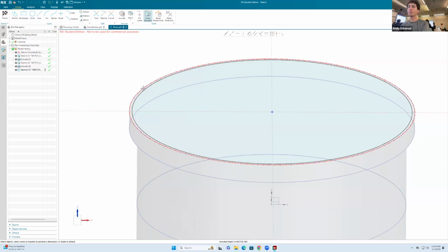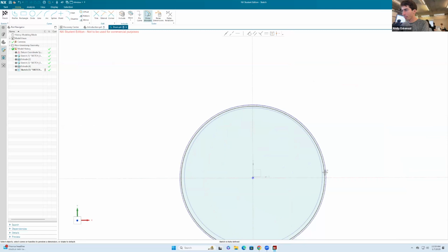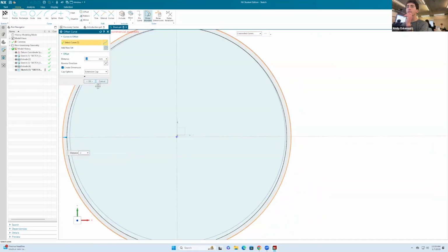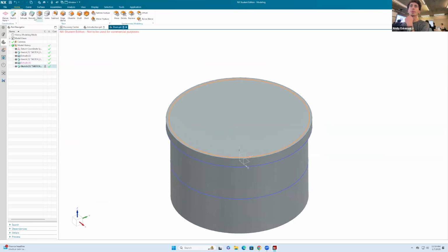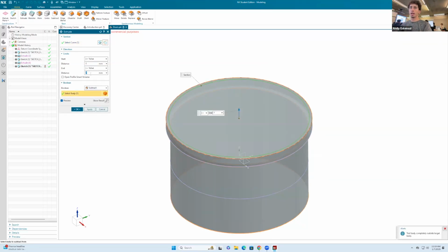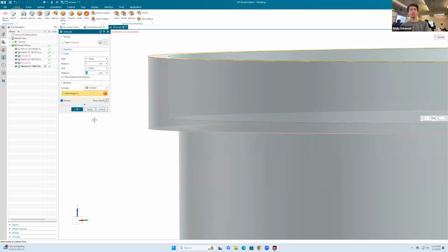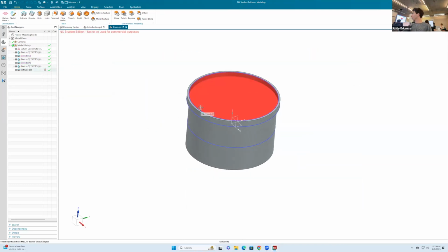I can go back here, right clicking it, I'll say -2. I want that to be like the drum. And I will go here to finish and then extrude. Instead of infer, I'll say subtract, and I will subtract by -6. So you can see in there, it gives you a little projection of how this would look. So we're creating a pocket, as you can see. Very good, it's starting to look a little bit like that drum that we had earlier.